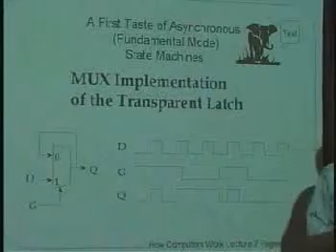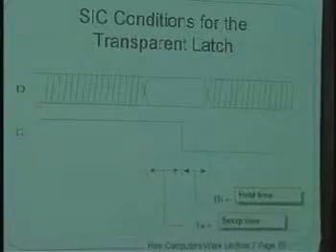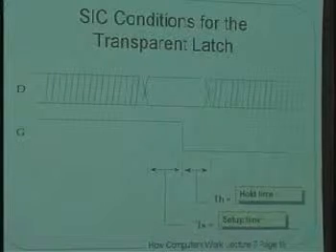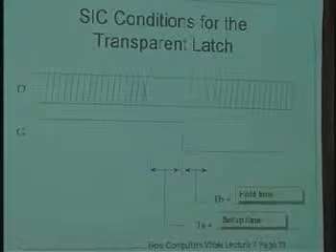And it turns out that that sort of limitation, saying only one input changes at a time, is exactly the same as the thing we talked about in the last lecture, saying that there should be a setup time and there should be a hold time around the instant that a memory element needs to capture whether an input is a 0 or a 1.